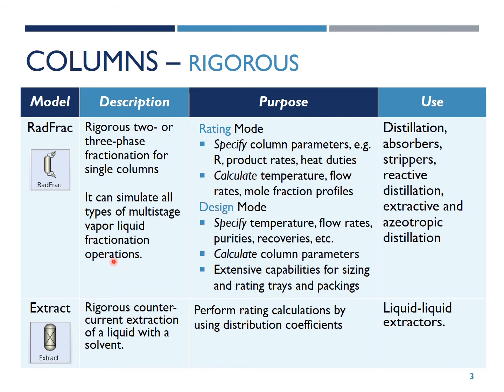The next model is Extract. Extract is a rigorous model for simulating counter-current extraction of a liquid with a solvent, or liquid-liquid extractors. It is appropriate for rating calculations by using distribution coefficients. Extract can have multiple feeds, heaters, coolers, and side streams.